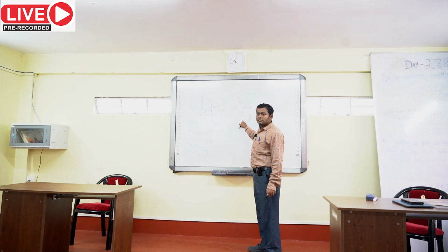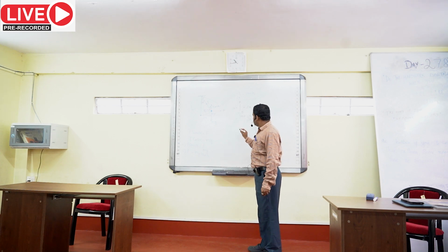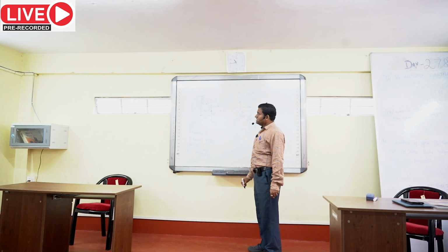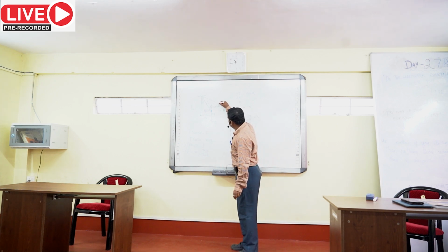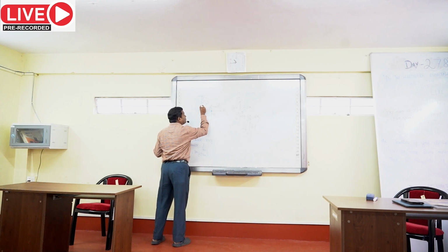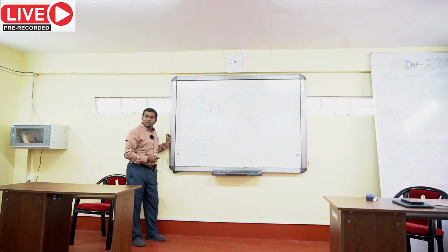But mg is constant. Wonderful. So it is the integral from 0 to theta of T dy, which means up to this point. Now, up to this point, what is the displacement in the y direction? This is y, but we can calculate y simply by the geometry without any integration.